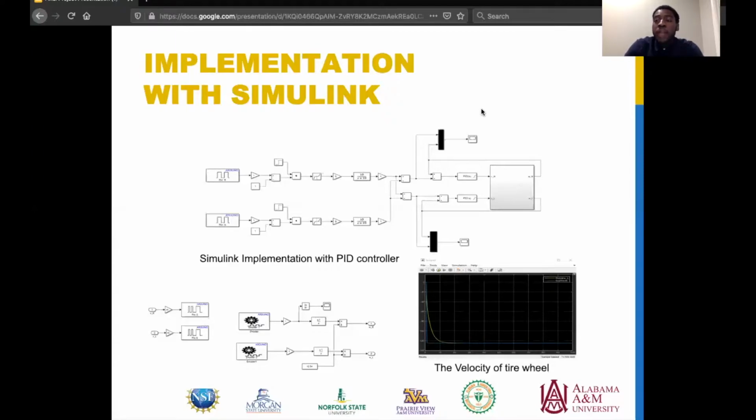The blocks represent math equations and modeling components. On the left, we have the set blocks that come with Arduino Due inside SIMULINK. All the way to the right, that box right there is our robot. Next to our robot, to the left, we have our PID controllers. On top and the bottom of our PID controllers, we have our scopes. And our scopes just read us our output.